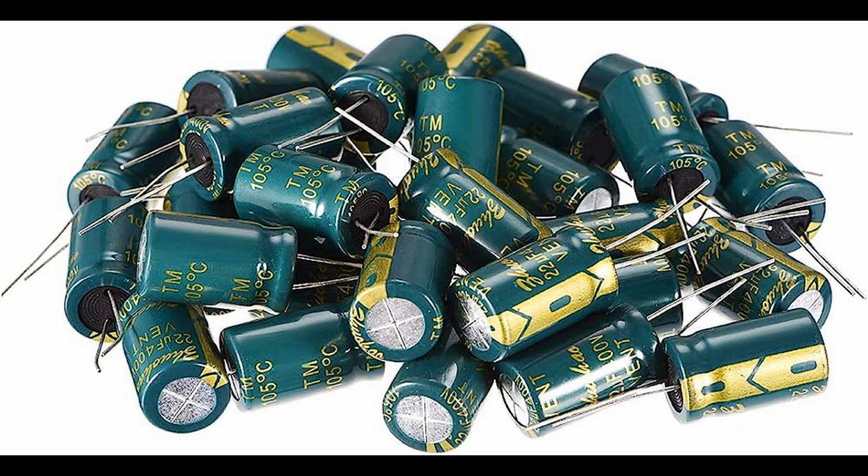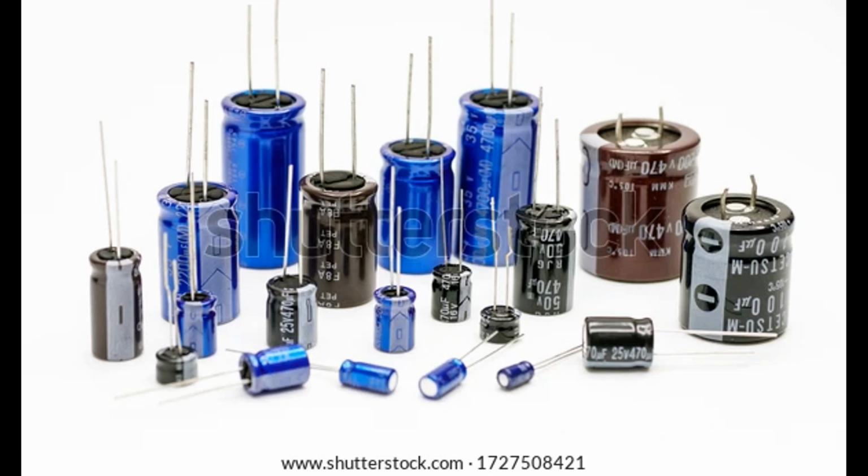Energy storage: capacitors with high capacitance values have the ability to store a larger amount of electrical energy. This energy can be discharged quickly when needed, making them suitable for applications that require short bursts of high power, such as pulse circuits, power supplies, or energy storage systems. Power filtering and smoothing: high capacitance capacitors are commonly used in power supply circuits for filtering and smoothing applications. They help stabilize the voltage output, reduce voltage ripples, and provide a steady supply of power to other components in the circuit.